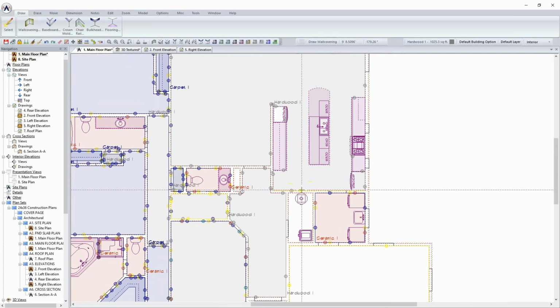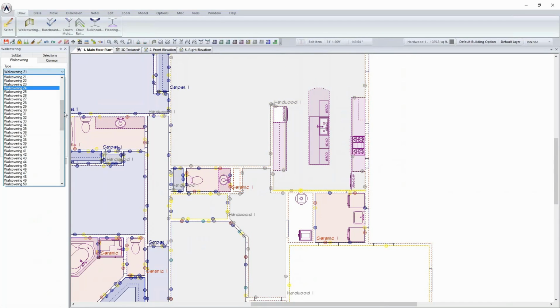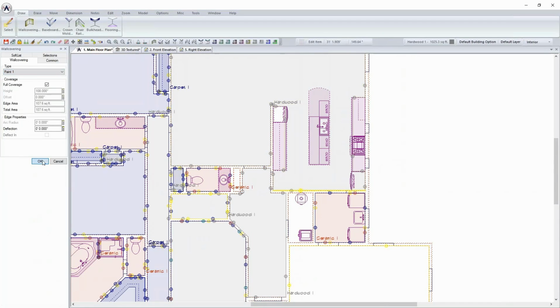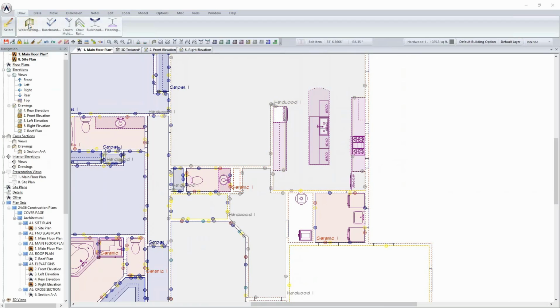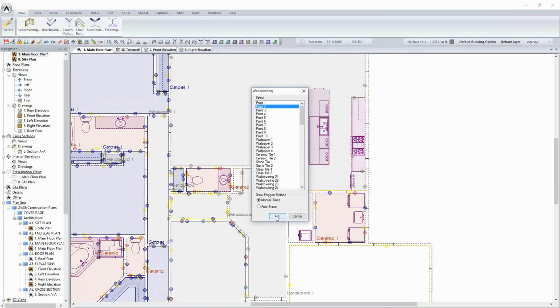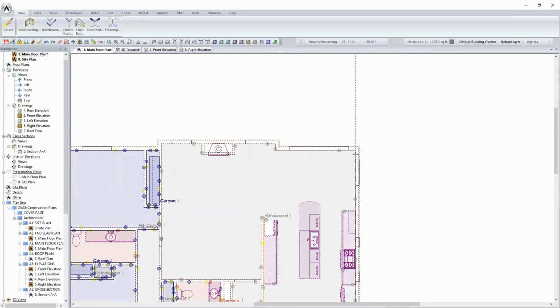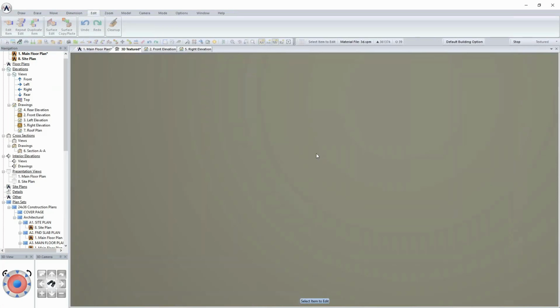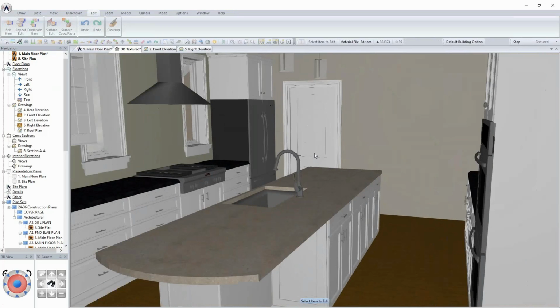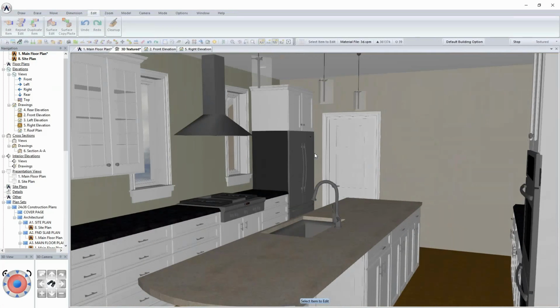And so in this case now, I've got wall covering 21, or if I just wanted to leave that as one of the paint colors that's there, paint 1. I could then come in through wall covering and pick paint number 2. In this case, I'm going to now manually trace this paint pattern down on the other 3 walls of the kitchen. Okay, so in this case now, I'm going to actually have different paint patterns that are going to be available to me for modification. So I could come in and I could do a surface edit on paint number 1.